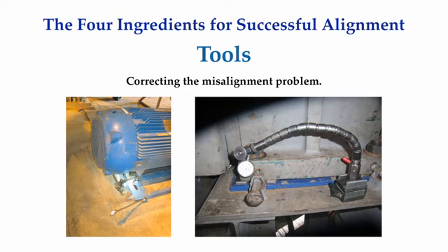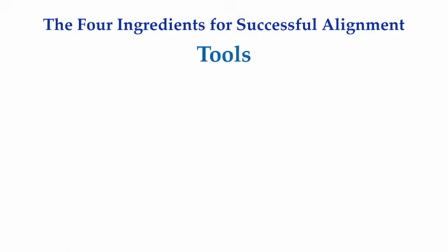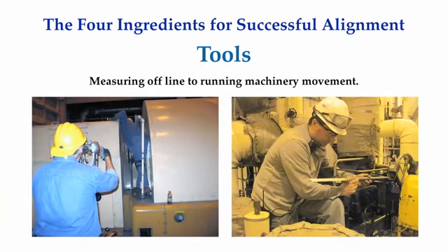Additionally, many people are unaware of the fact that certain types of drive systems should be intentionally misaligned. Once machinery is started, heat generated from friction in the bearings or heat generated from compressions of gases or from pumping hot process fluids, and the expansion or contraction of attached piping, ductwork, or frames, and concrete foundations will have a tendency to move the shafts to some other position than where they were at when offline.